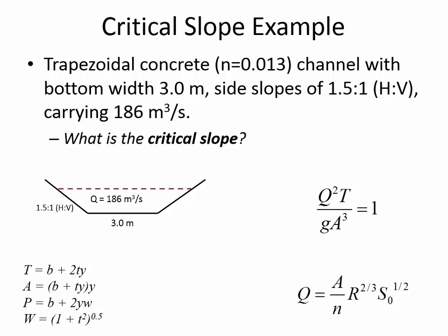That means critical conditions. When this formula is equal to 1, what we're solving for really is the critical depth. Okay, so y sub c, if you put that into your calculator and solve, y sub c is going to be 4.121 meters. It's the critical depth.